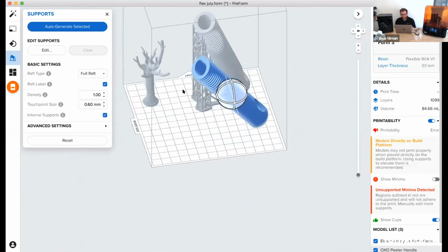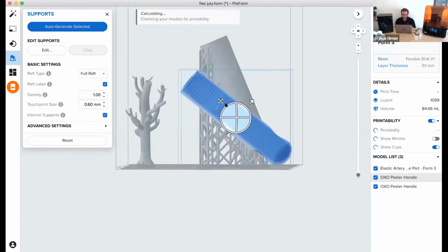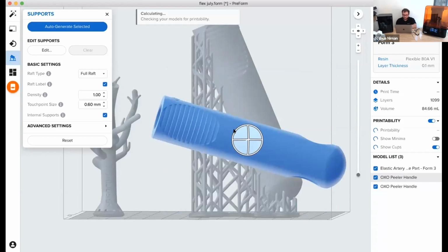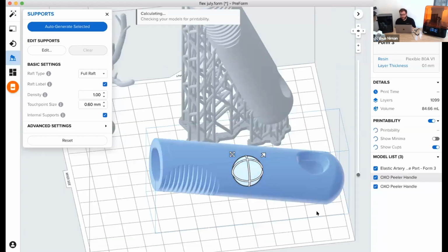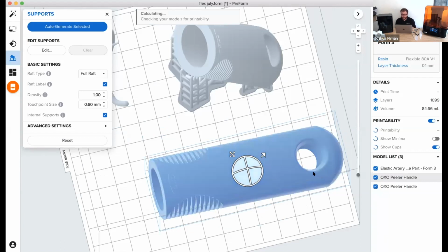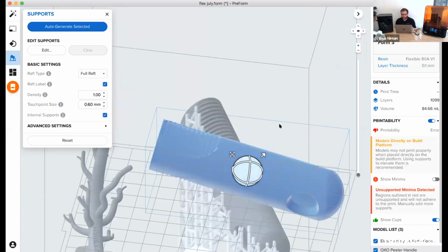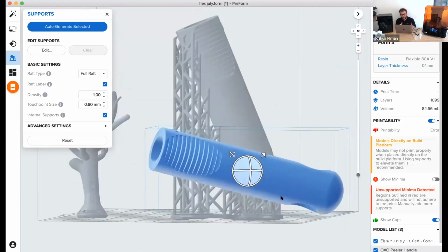A lot of our support documentation and a lot of contemporary wisdom about this is to keep it as low and flat as possible, right? Because if I come down at an angle like this, suddenly I have a ton of space to anchor supports to the platform. I'm going to have really good adherence. I'm going to have a really stable structure. My sort of tripod base has gotten a lot wider, and so it's a lot more stable. That's awesome, but there are trade-offs there, right?